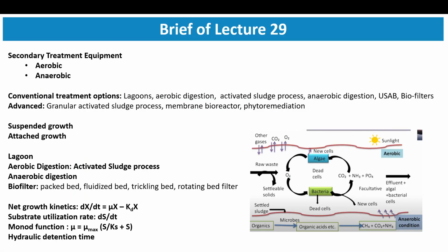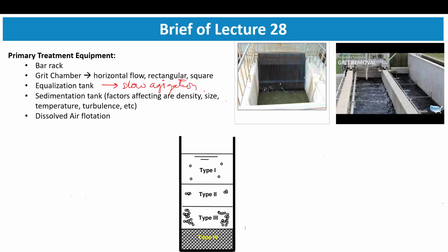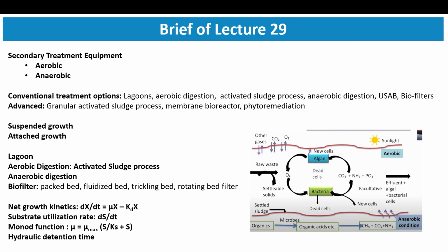Next class talks about, like, this class was about the treatment of water through primary treatment, where we are removing some suspended solids, some coarse material, basically through gravitational force, or through some screens, or by the flotation method, dissolved air flotation, which removes lighter density material. Now in case you have